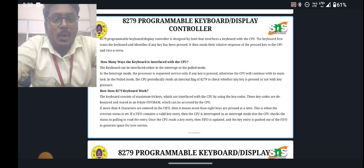If the FIFO contains a valid key entry, then the CPU is interrupted in the interrupt mode, else the CPU checks the status by polling to read the entry. Once the CPU reads a key entry, the FIFO is updated and the key entry is pushed out of the FIFO to generate space for new entries.